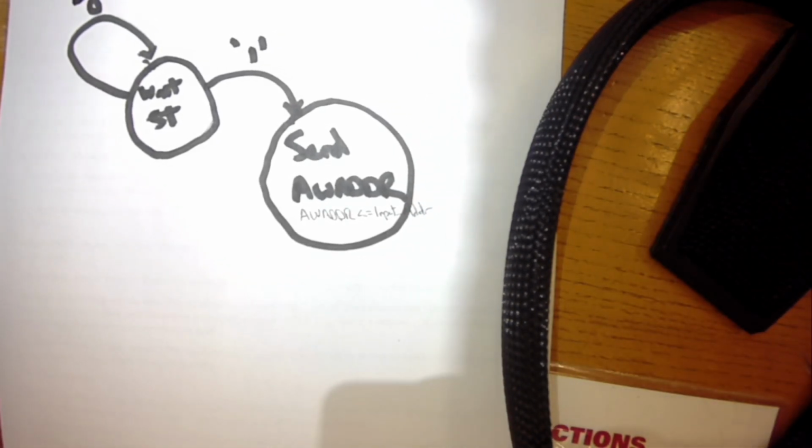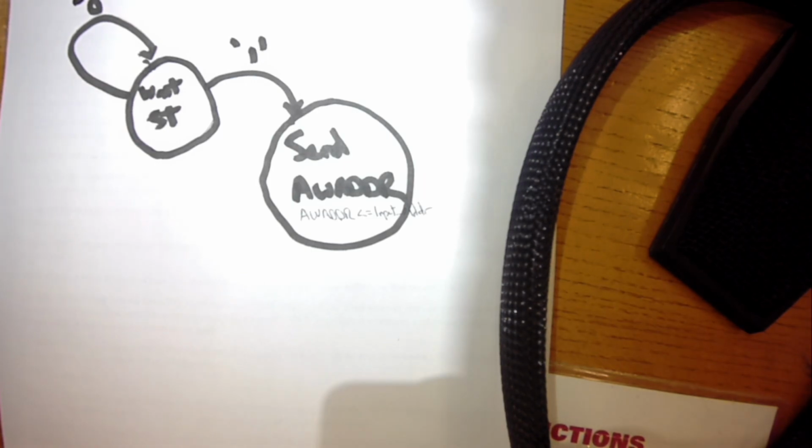I'll just have to move it around a little bit. That's setting my AW address to the input address. For me, at least, I would just have that be, you don't even need a state machine, you don't even need a process if this is just one line of kind of data flow logic. When state is send AW address, set AW address to input address. Or you put it in a process, but it wouldn't need to be a clock process. When we're in that state, I'm sending that address. What also should I be sending when I'm in this state? The valid signal.